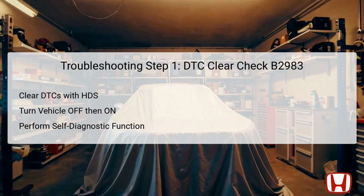The first troubleshooting step involves verifying the DTC by clearing it using the HDS, or Honda Diagnostic System. This specialized tool allows for an effective reset of the vehicle's error codes. Following the clear, transition the vehicle into the off/lock mode, and then back to the on mode to check if the issue persists. It's critical to perform a self-diagnostic function with the HDS or the climate control unit itself to verify if the DTC reappears.